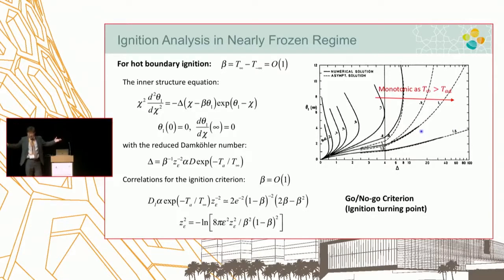Guess what happens? We are talking about the situation where fuel and oxidizer are in opposite streams, but on one side, the air side, the temperature is hotter than the adiabatic flame temperature. Under that scenario, there's no extinction, or ignition for that matter. Everything just sweeps through in a continuous reactor system.